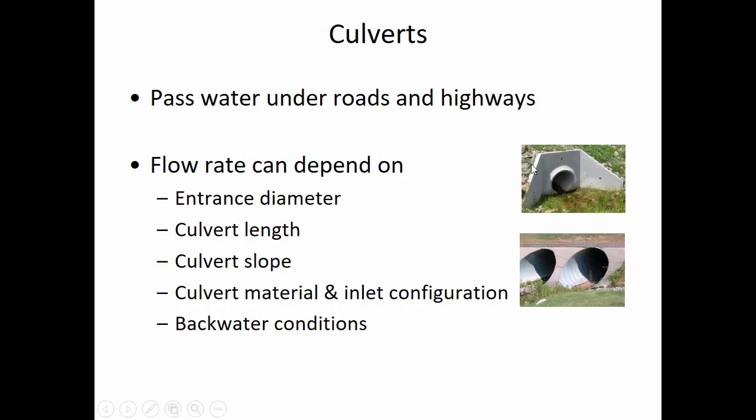So how much water gets through that pipe? Like I mentioned, my driveway, it's a 24-inch pipe. Why did I choose a 24-inch pipe? Well, it's because it wasn't that much more expensive than the 18-inch pipe. The 18-inch pipe probably would have been big enough, but having a larger pipe makes it easier to clean, so there's some maintenance advantages, and the cost difference was negligible. But it's not always where it's just going to be a little bit more. Sometimes it's going to be significantly more, and so how big of a pipe you need,